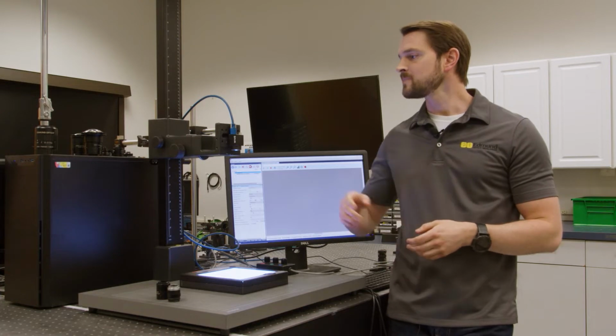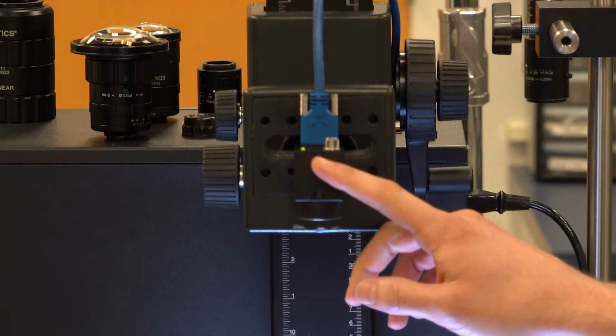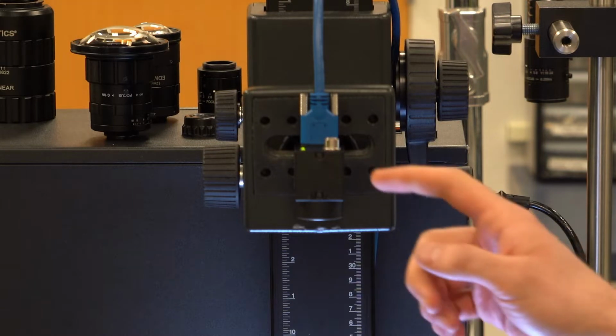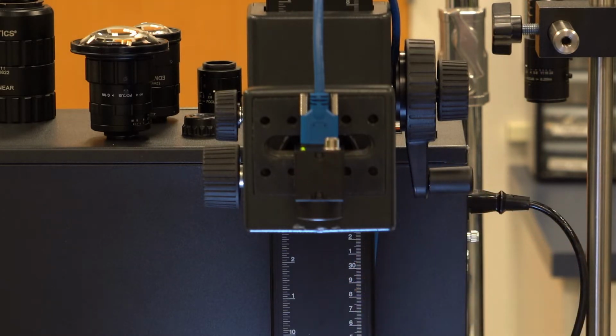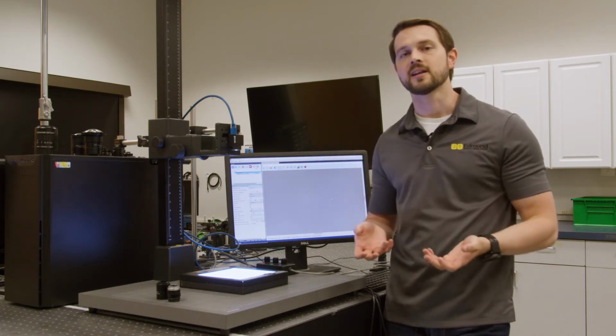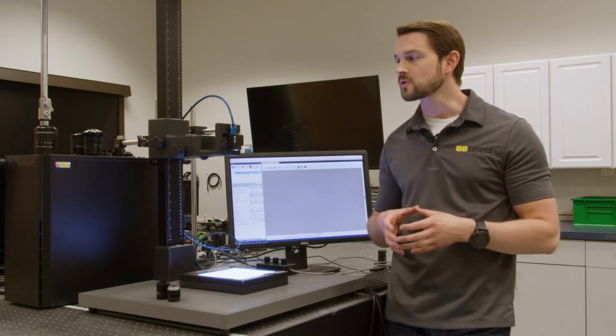And in order to do that, I have got a FLIR camera set up here. This has the IMX 183 sensor in it. This is a 1-inch sensor with 2.4 micron pixels. I actually have taken this sensor and done an AOI on it. That's an area of interest to make this a 2/3-inch sensor.